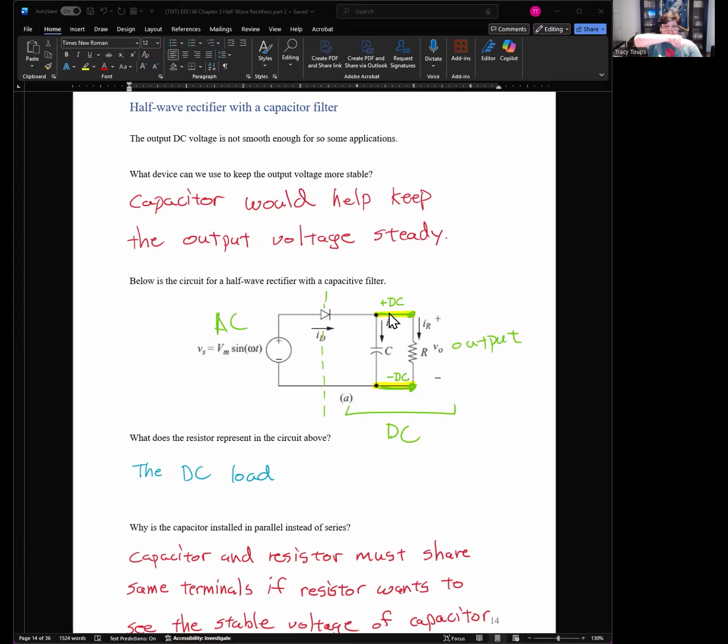The voltage is a half wave. The positive cycle is what we rectify. And it's a flat 0 and another positive half and a flat 0. That's a pretty harmonic rich environment. We don't really like that. We want to get that hump to flat DC as well. Notice that we use inductors to flatten out the current. We know we can use capacitors to flatten out the voltage, and this is exactly what we're going to do. We're going to add a capacitive filter.